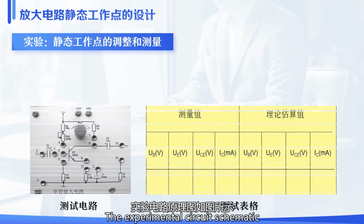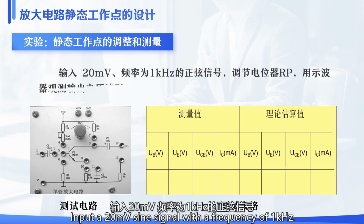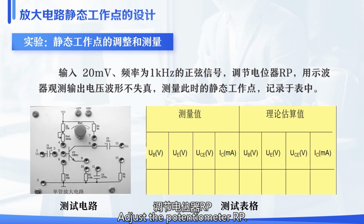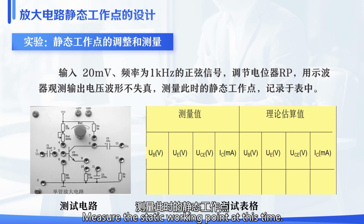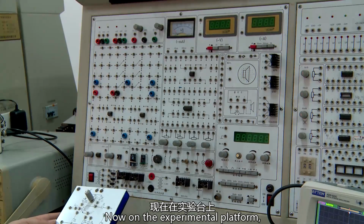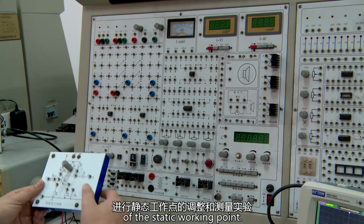The experimental circuit schematic is shown in the figure. Input a 20 mV sine signal with a frequency of 1 kHz. Adjust the potentiometer RP. Observe the output waveform without distortion using an oscilloscope. Measure the static working point at this time. Record the experimental data. Now on the experimental platform, carry out the adjustment and measurement experiment of the static working point.